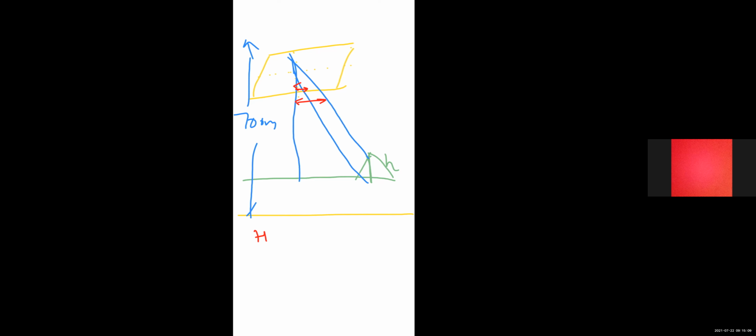So we can write here r equal to 700 meters, h average equal to 250 meters. So relief displacement equal to 112.5 minus 82.40 equal to how much? 30.1 mm. So what is the scale?